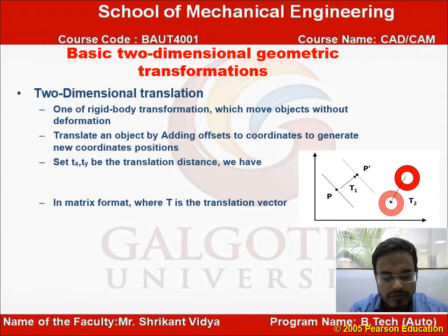For software purposes, we can use a scale command, move command, and rotate command for transformation in the software. Visual transformation is the transformation in which there is no change in either the geometry or the coordinates, but a copy is only placed at different places where required. So in AutoCAD, we require the zoom command and pan command for visual transformation.